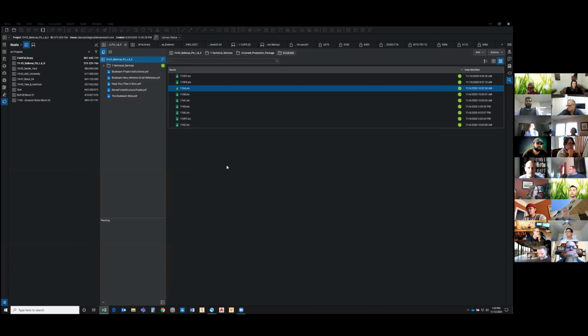There's a functionality in Bluebeam called slip sheeting, where you choose the document you're trying to replace, and then you choose the replacement document. You have to use the slip sheet functionality, because otherwise all your links are broken. If you just take it off and re-upload it, it doesn't know that new document, and all the links in the shop drawings or anything else don't know that it's there. Gotcha.